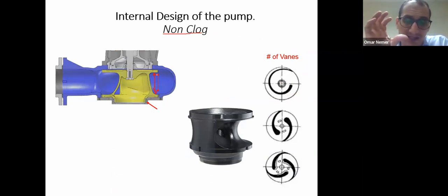This big passage lowers the ability of the pump to control the liquid, and also gives a higher possibility of turbulence of water. These things will lower the efficiency. This is a negative consequence of this design, but we cannot avoid it. We need it because we want to pump wastewater.